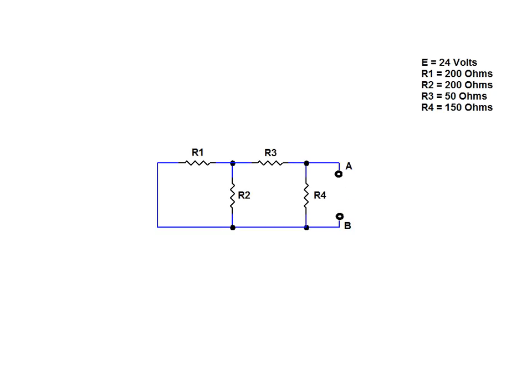To do this, we must reduce this resistive network down to a single equivalent resistance. To begin the reduction, we calculate the equivalent resistance of R1 in parallel with R2 by using the product over sum rule.